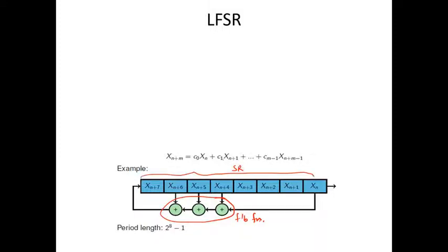So the two parts of the LFSR are the shift register with n flip-flops and the feedback function, which is normally realized using modulo 2 adders or XOR gates. They are simple XOR gates. Modulo 2 addition is nothing but the XOR operation. Yes or no? So all of you remember modulo 2 addition is the same as XOR operation. You can see the defining equation we wrote there. So what do you think the C0, C1, up to C(n-1), all these will represent? Anybody?